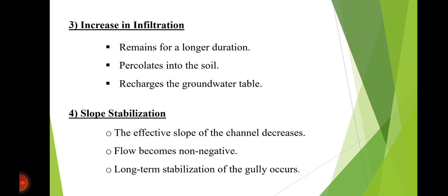So, infiltration of water: the temporarily stored water gets more time to infiltrate into the surrounding soil. This improves soil moisture and can contribute to groundwater recharge. Safe passage of excess water: when the water level rises, excess water passes over the crest through the designed outlet or openings of the structure. Proper design prevents uncontrolled overflow and structural damage.